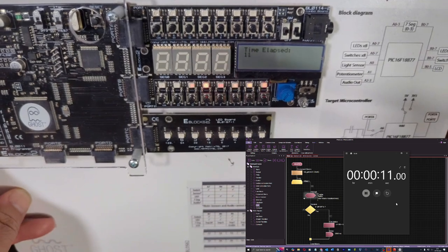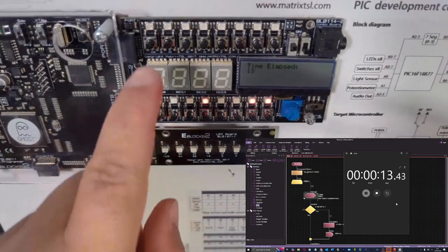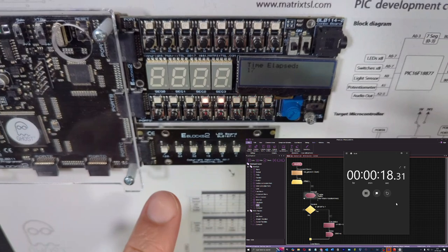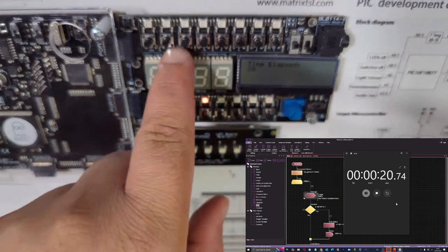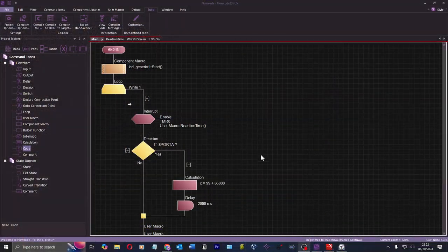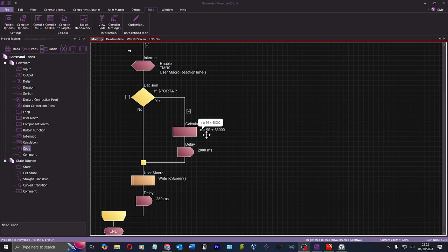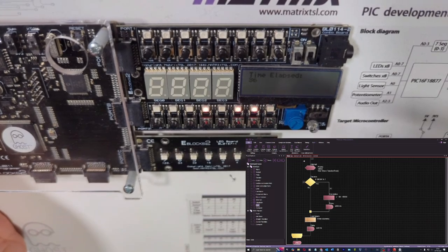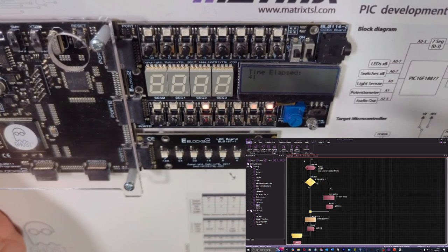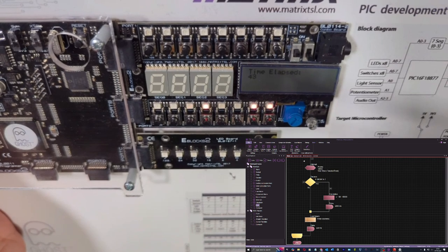All right. So I have a 2-second delay when you press any of these buttons, apart from A0. I don't know what happens when you press A0. If you press any of these buttons, it should go into this code here, and it should do x is equal to 99 plus 65,000, and then wait 2 seconds. That's what it should do. Then the timer interrupt should interrupt it twice that second and still continue updating that value.